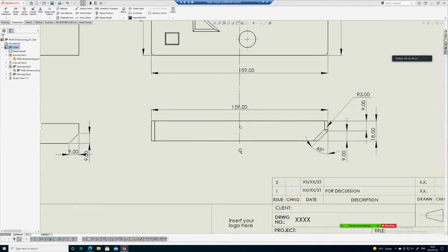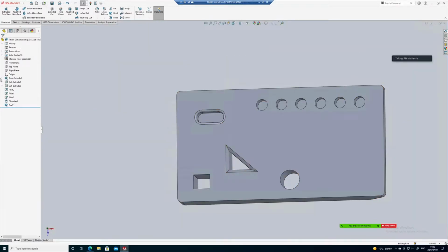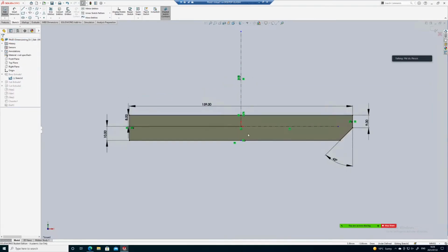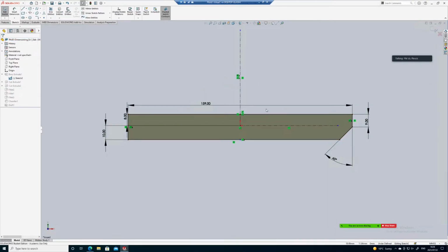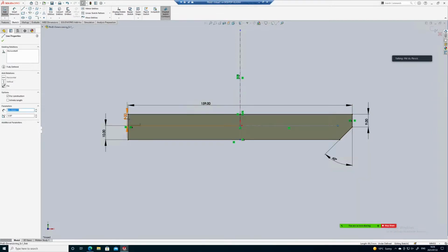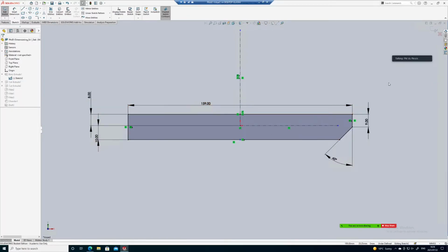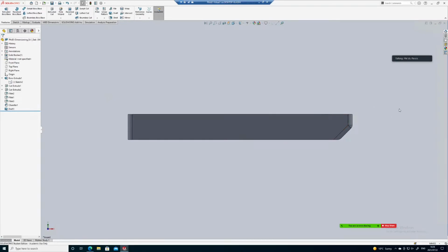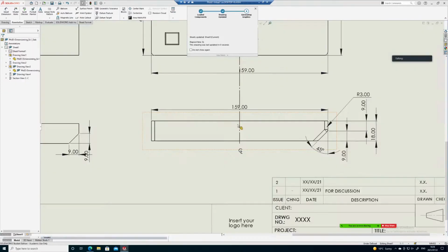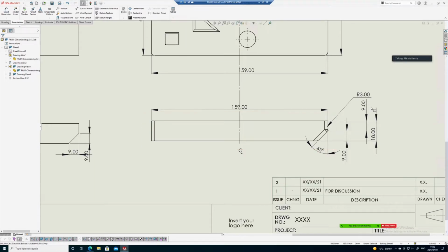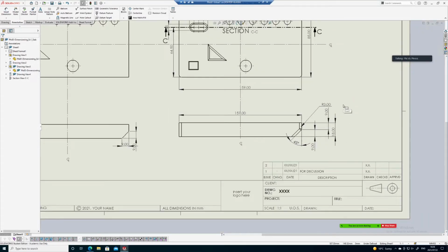Those dimensions come from my sketch, and they are present because I positioned this shape relative to that line there by using 8 and 10. So it's actually carried those dimensions through. Sometimes you have to watch what the magic button does, because it'll take all your dimensions through, so sometimes you have to remove some of them. Any questions about that?